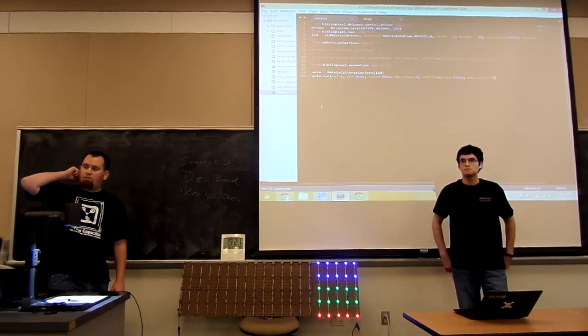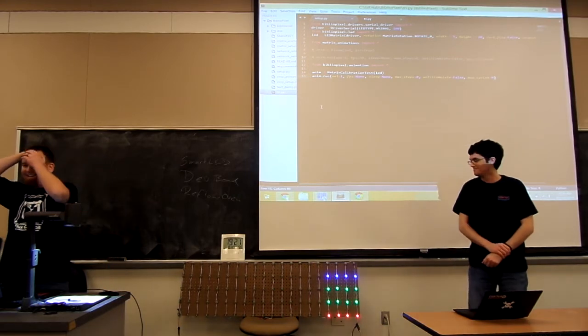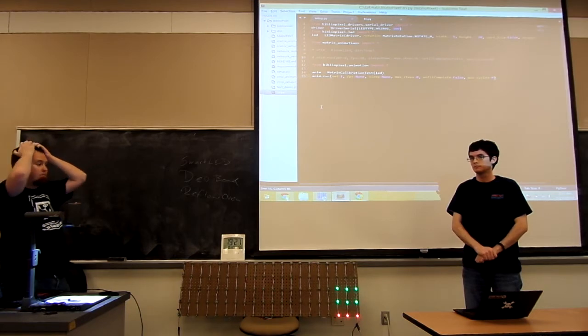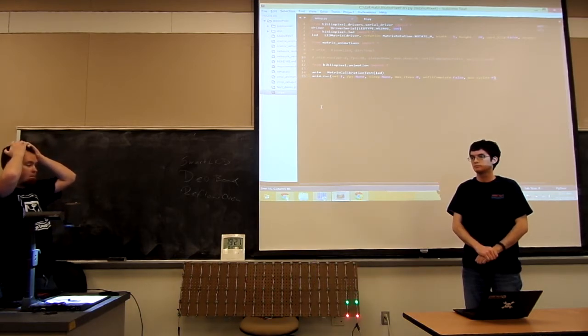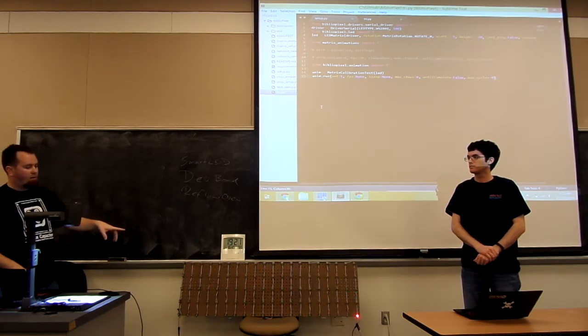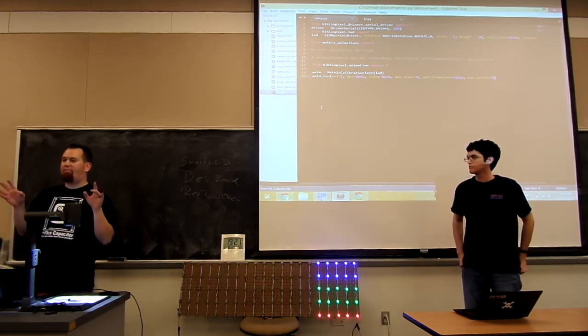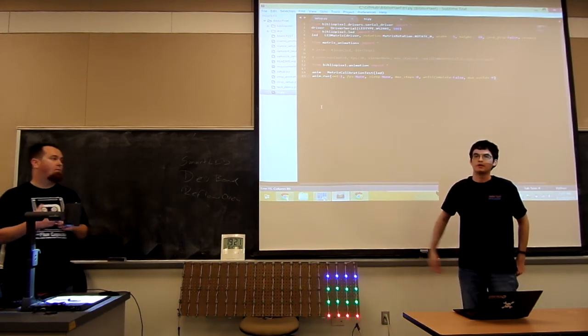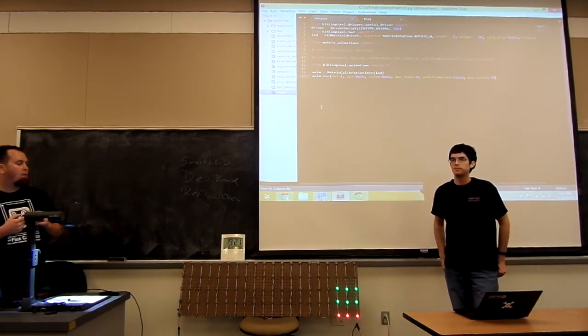So I'm new to this world of things. If I may ask, how much does a strip like that cost? And you said that was SPI? So you're doing SPI communication to drive those LEDs? Well, we're doing serial to the all pixel, and then the all pixel is figuring the rest out. It is SPI in this case. The lights themselves are an SPI communication.